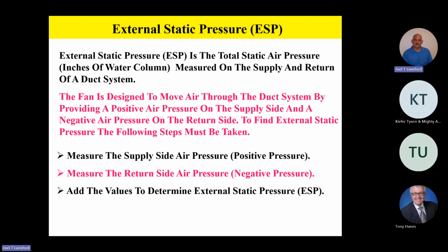Now, guys, remember the fan's designed to move air through the duct system by providing a positive air pressure on the supply side and a negative air pressure on the return. To find external static pressure, we got to do the following steps.